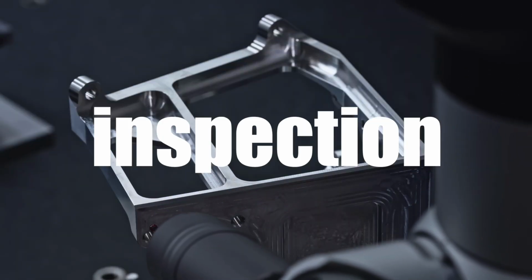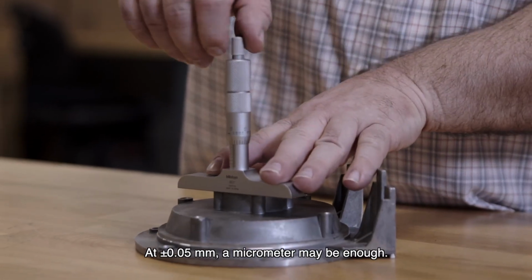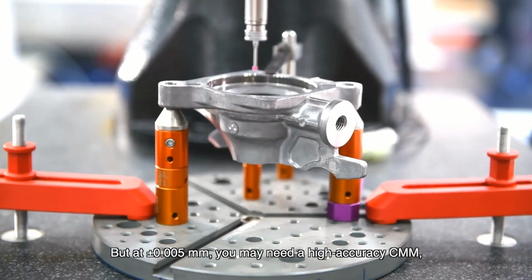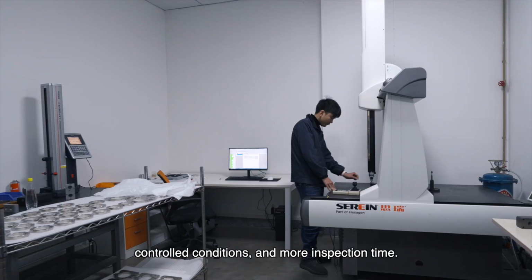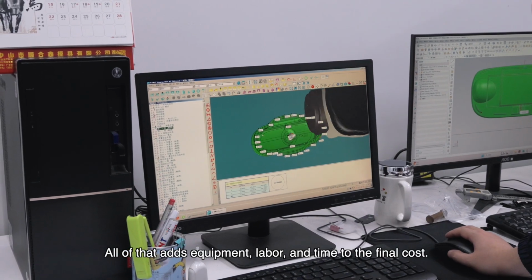Next up, inspection. At plus or minus 0.05 millimeters, a micrometer may be enough, but at plus or minus 0.005 millimeters, you may need a high accuracy CMM, controlled conditions, and more inspection time. All of that adds equipment, labor, and time to the final cost.